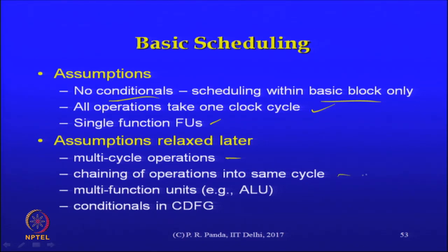We can have chaining of operations into the same cycle, means that there is one operation dependent on another operation, right. Both of them could be scheduled into the same clock cycle if enough time was there. You could have multi-function units, you could have ALUs that are capable of performing more than one operation type, you could have conditionals and so on. All of these are generalizations that take us in different directions, but just to simplify the algorithm, let us just make these assumptions for now.